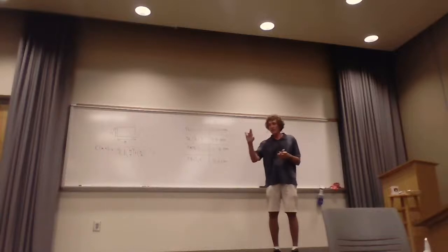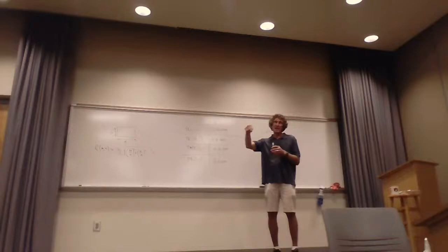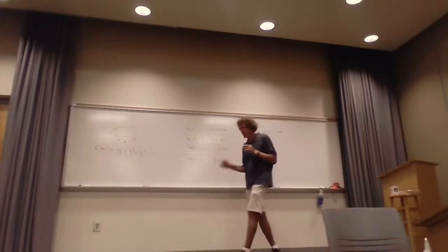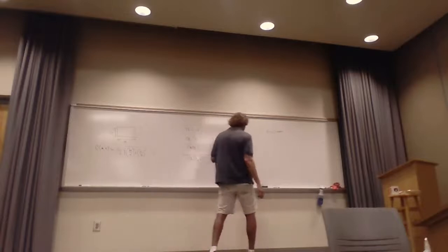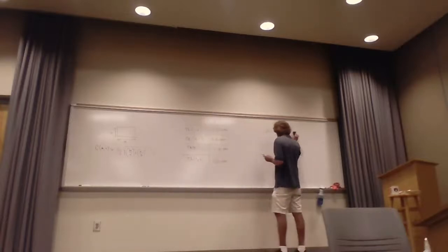In other words, if you put a voltage on a probe in a waveguide below cutoff, you're going to draw current, but you're not going to propagate anything. And the ratio of the voltage to current will be an impedance, but it'll be strictly imaginary. And I believe it's going to be a positive or a negative J. It'll be capacitive, I believe, but I got to check that. We don't normally delve into that in an undergraduate course.